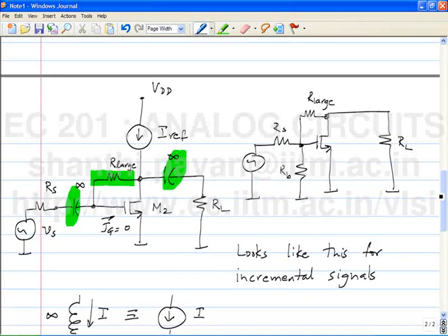The first one being the gate simply being biased by a string of resistors. Alright? I mean, you've seen the first circuit where RA and RB were a resistor string. You've seen a second example where we use a current mirror. We've seen a third example where you can do what the current mirror does equivalently, but use the same device. So, can somebody comment on the swing here versus the swing in this current mirror case?